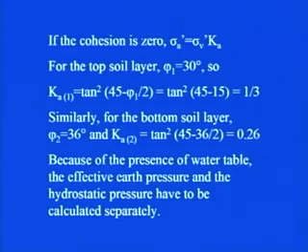Before solving this example, one thing I would like to tell you is that you should always keep in mind that you first determine the effective vertical stress at any particular depth z, and as I told you, if you multiply that by the coefficient of earth pressure, that will simply give you the lateral earth pressure at that particular depth.